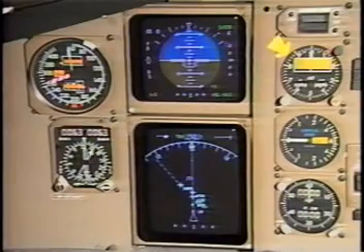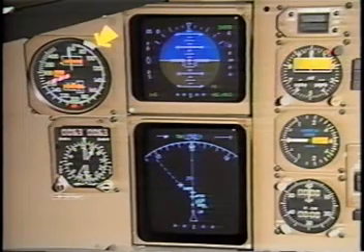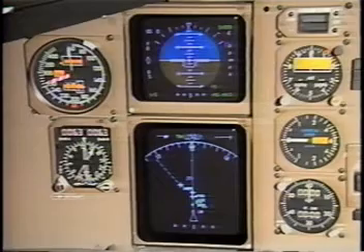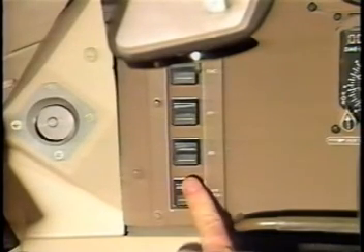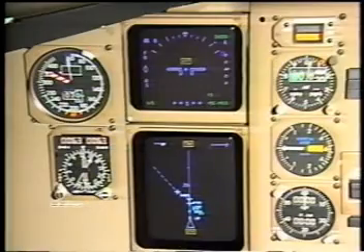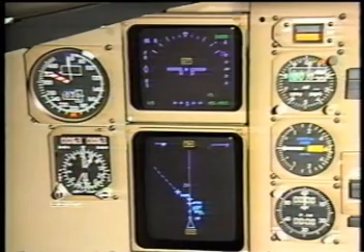If flags also appear on the electric altimeter and Mach airspeed indicator, the faulty component is generally the air data computer. Select the ADC alternate instrument source select switch to confirm this conclusion. If flags do not appear on these 2 other air data instruments, the problem is generally located in one of the IRUs.